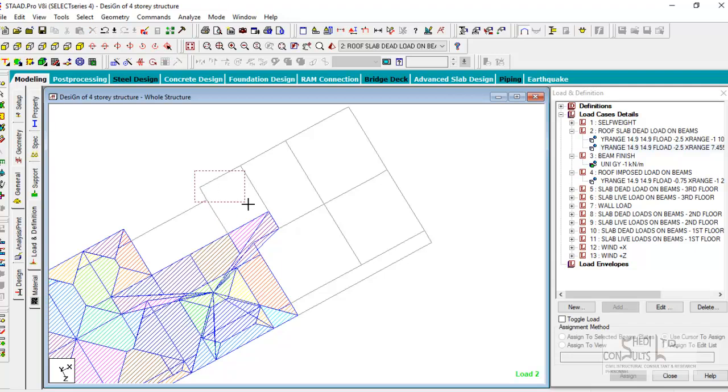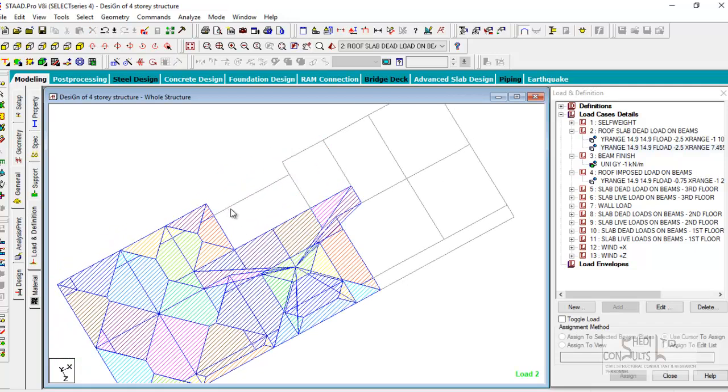Okay, so this is another panel. I need to define this panel separately, then define this panel, and then define this panel, so that you don't create duplicate loadings. It's very important that you do not duplicate loads or load the beams wrongly. So the panels have to be defined carefully, correctly, and meticulously. So I'm going to define this other panel now.